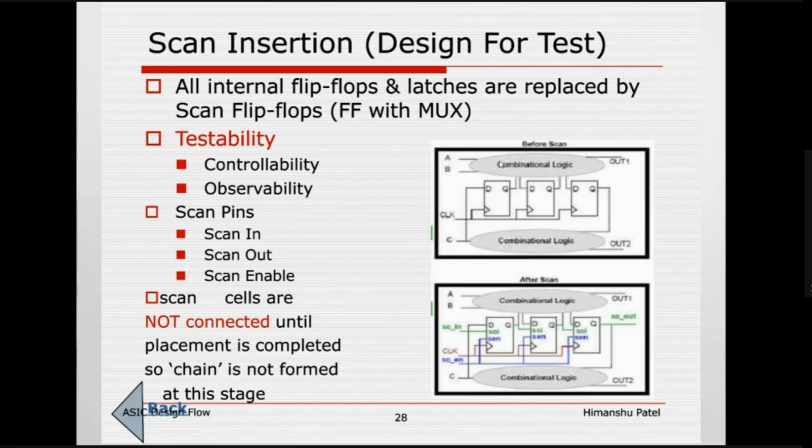So the only way to do DFT is to use the existing flip-flops in the design. We are using existing flip-flops in the design, which are the fundamental blocks of driving the data and capturing the data. So one bit of data can be stored in, or toggled out, using this flop. This particular flop is already connected physically, logically in the RTL code.